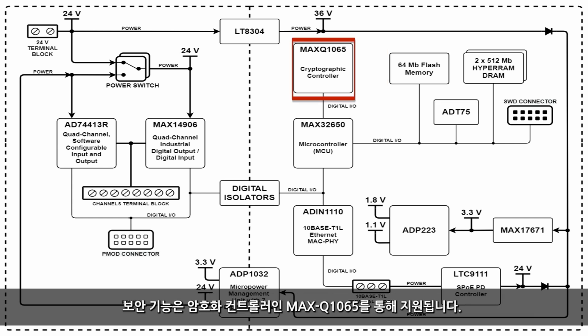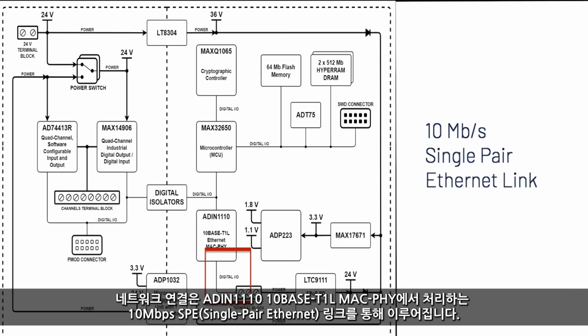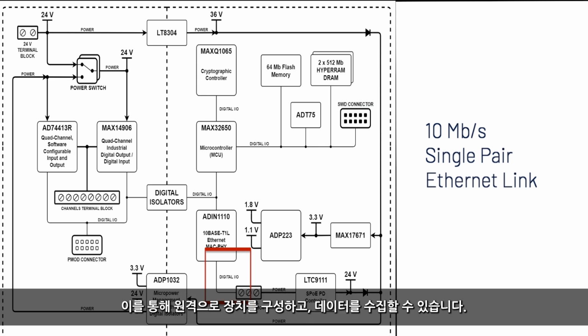The security features are ensured by the cryptographic controller MAXQ1065. Network connectivity is enabled via a 10 megabits per second single-pair Ethernet link handled by the ADIN1110 10-base T1L MAC-PHY. This permits remote device configuration and data acquisition.